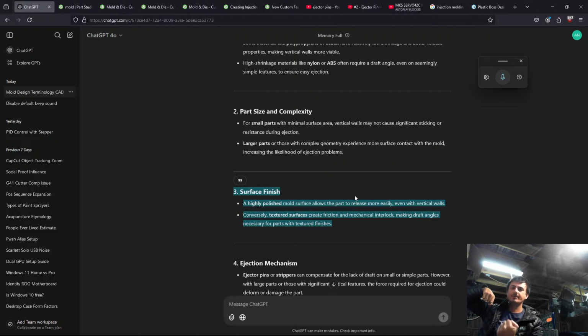Let's see, you somehow fasten to the cavity and the core, right? And then you use a 3D print. You're using 3D printed molds in this case, and then you measure the force required to pull the thing apart. So you just measure that over time, and then you machine the cavity and core, and you see, is it less? Because it probably is less. That would be a very fun experiment.